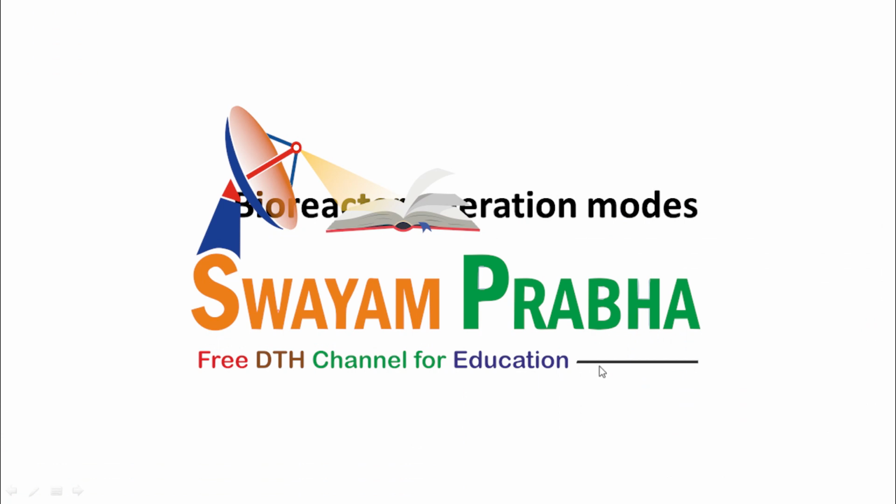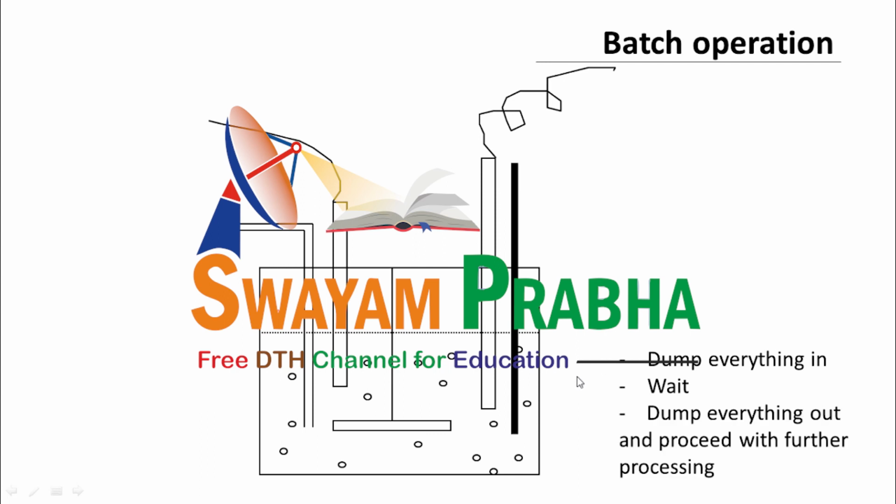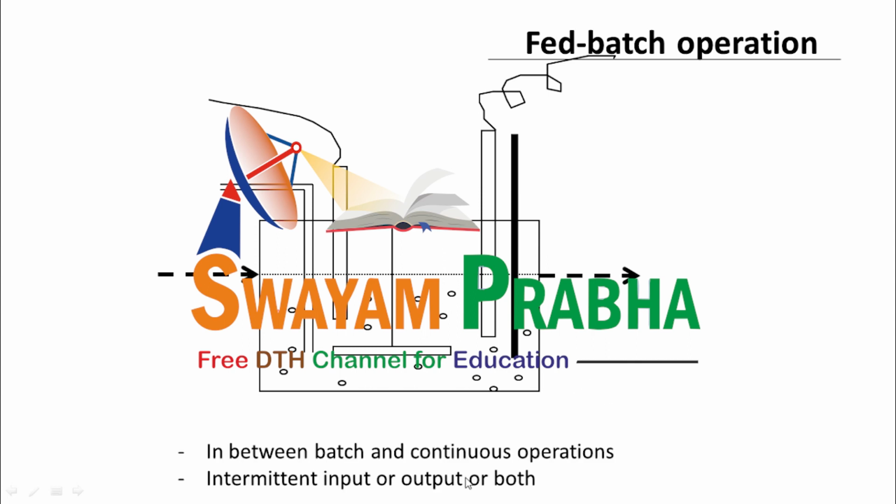Then we said that the bioreactor could be operated in a few operation modes: the batch, where we dump everything in, let the process happen, and dump everything out and proceed with processing. Continuous operation, where there is a continuous input and a continuous output. We are usually interested in the steady state operation, which occurs for most of the time. The initial paths could be at unsteady state, and the startup and the shutdown paths could be at unsteady state, which we are not normally interested in. And then the fed batch operation, which is somewhere in between a batch and a continuous operation, maybe intermittent input or intermittent output, or both.